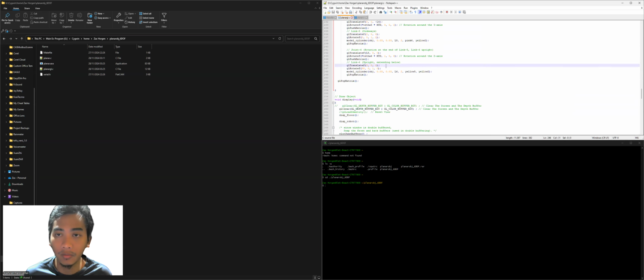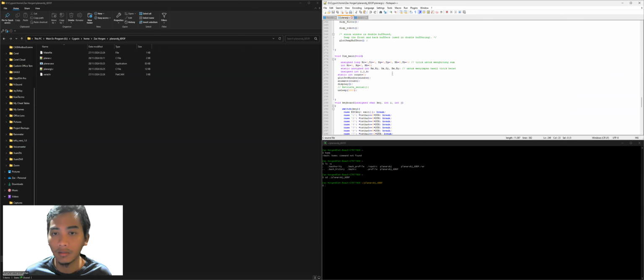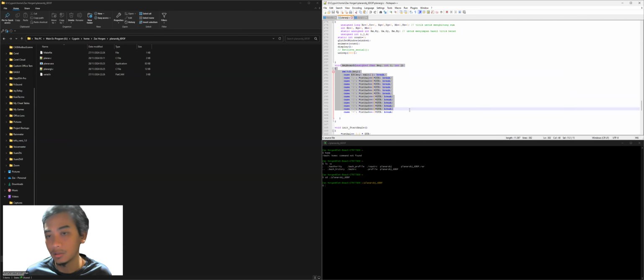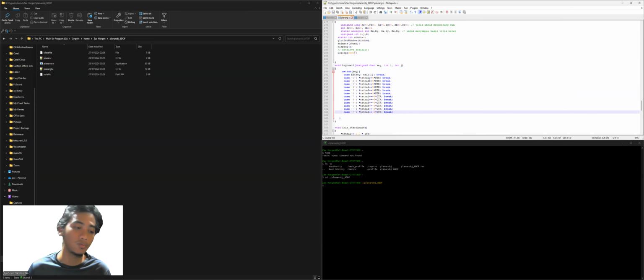After we're done with the position and the rotation pivot point angle, we're going to make the keyboard control to rotate manually. In this case, we're still doing it manually to ensure that the movement or the pivot point we are on is actually the right one. So the theta one will be controlled by button number 1, 2, 3, and so on. All of them are keyboard key strokes. If we press the button, it will rotate theta one on link one, joint one, by 5 degrees.